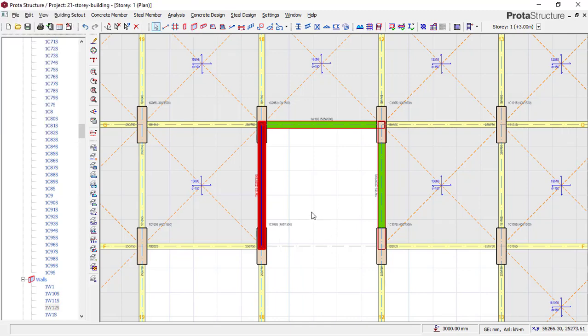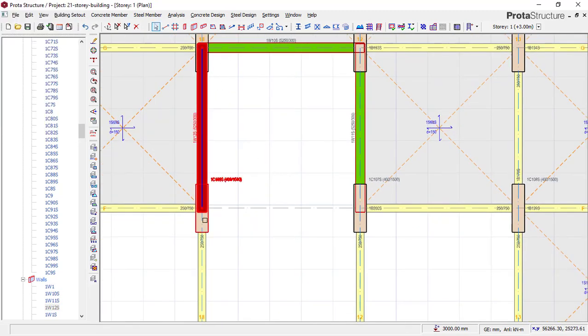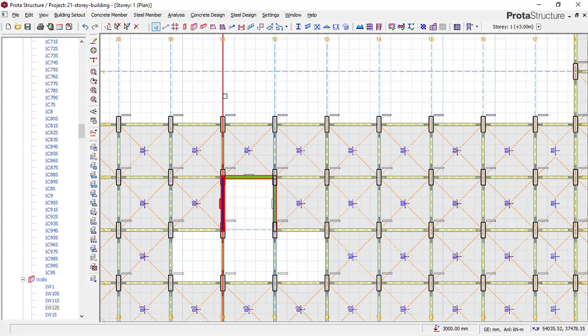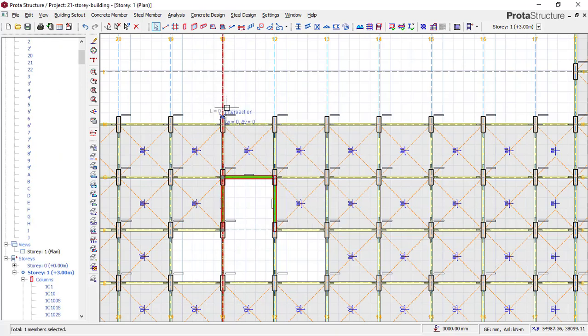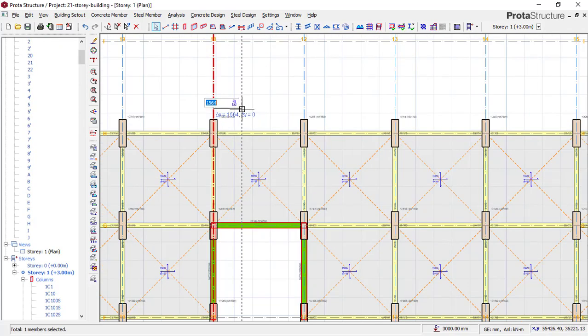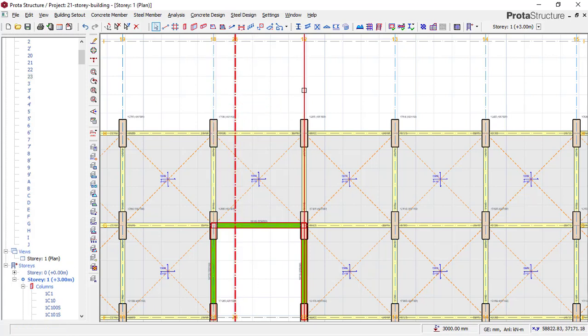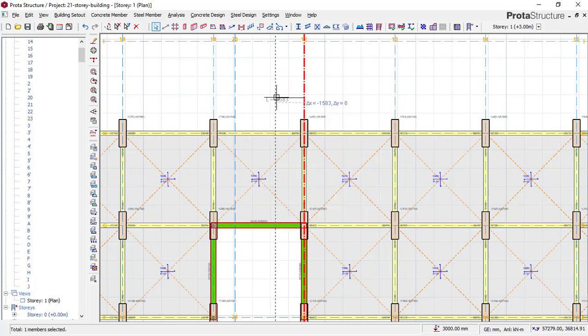Then we have to input our lift entrance by offsetting the grid line. This one, let's say the distance is 1.2, so say 1200. Enter. And then we'll click on this one. Distance from here, let's take 1500, so minus, because it's going the other direction. Minus 1500. Enter.